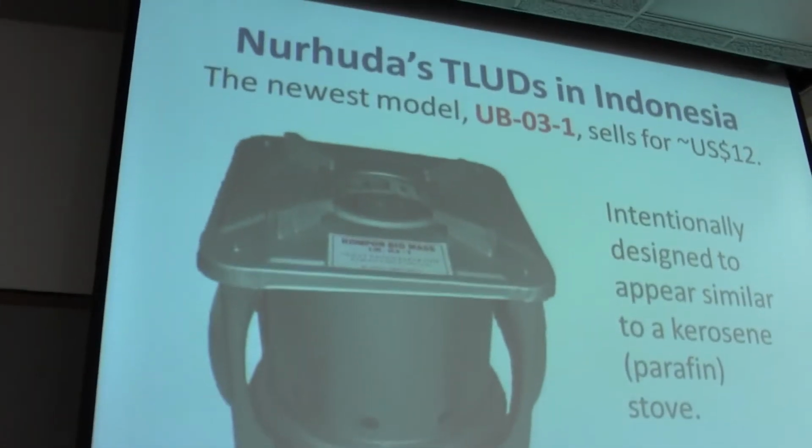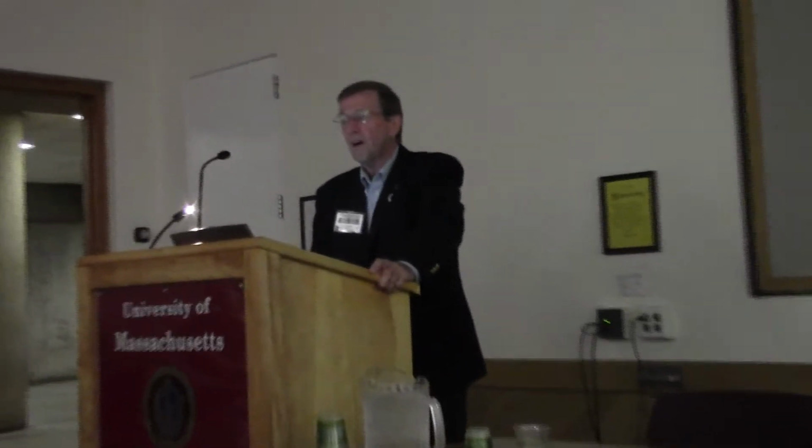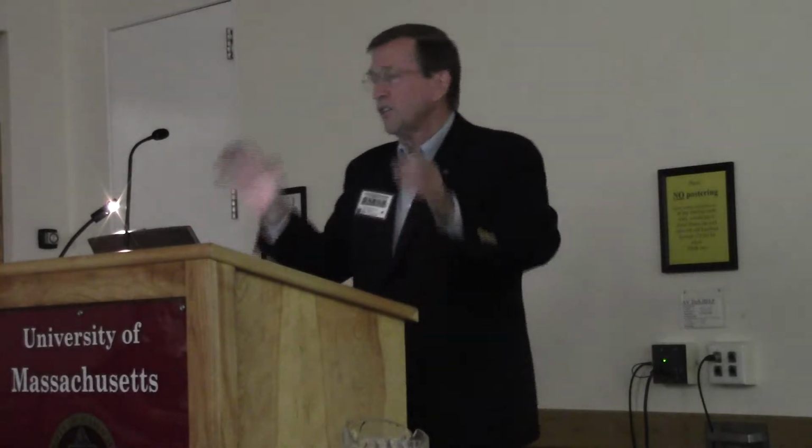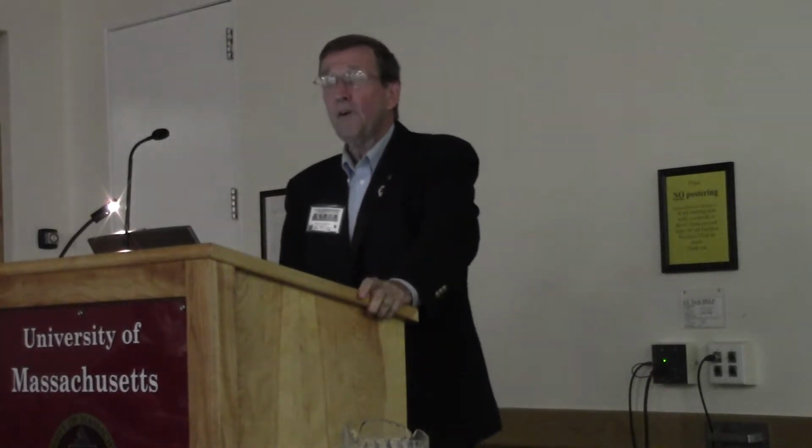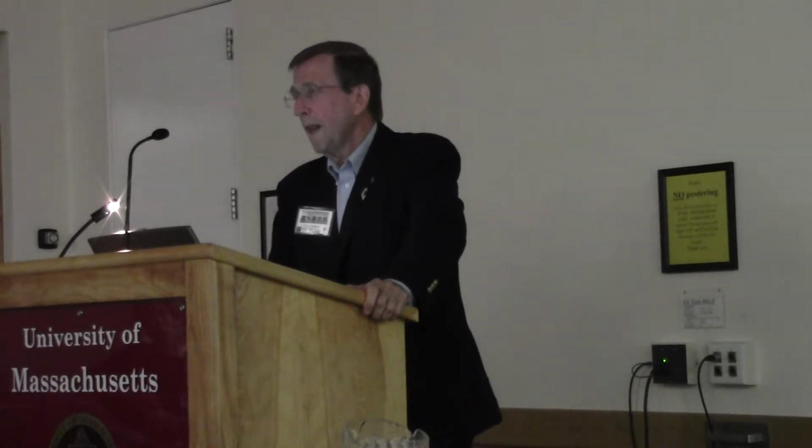There are other cook stoves of the TLUD style. This one is out of Indonesia. I can criticize all kinds of stoves. I won't put it down in writing, but this stove lacks a chimney, a small little riser to get the draft going, and therefore it is weaker. These are discussions I can go into with you about how you can make something go. If you're at higher elevations above 1,500 meters, you're going to need more riser. Lots of little tidbits of how to make it go.